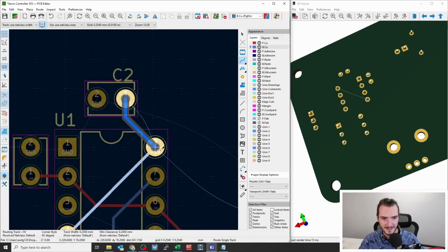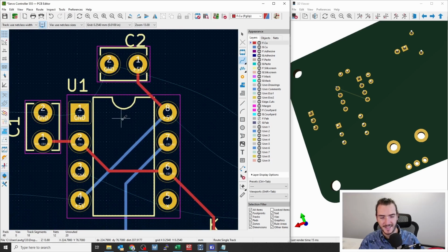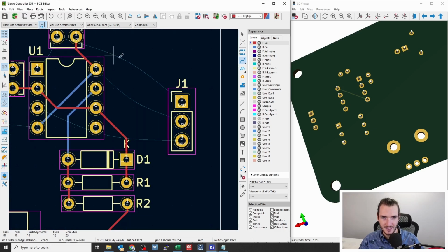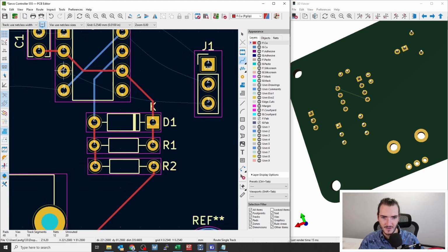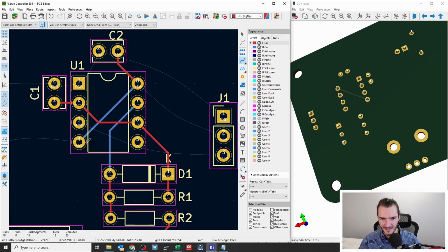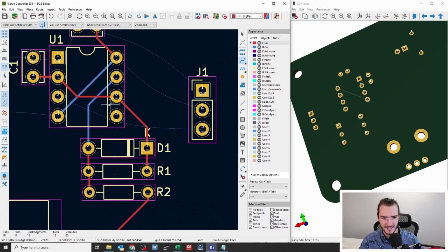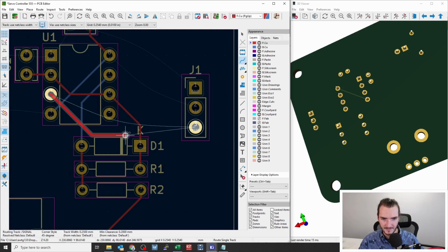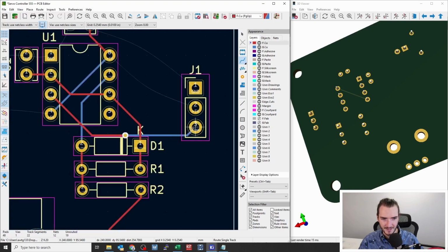We can put in our power supply decoupling cap, and I'll prefer to put as many traces as I can on the top side to keep a nice clean back side. Now here we have a signal that we need to run around. We've kind of painted ourselves into a corner. This is not a very critical signal though, because it's a low frequency signal, so we could route it around, but what I will do instead is sneak it. What can I do? I can sneak this between these pins or out here and then drop a via. So I can drop a via and then run it over to signal.